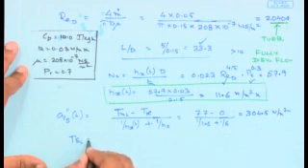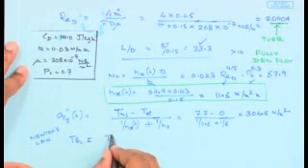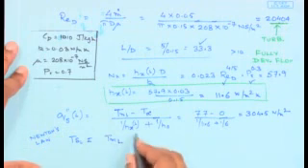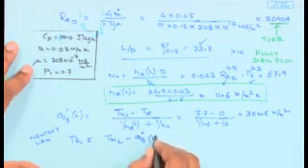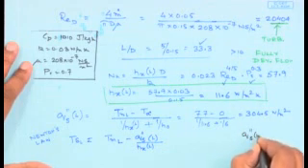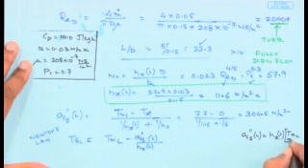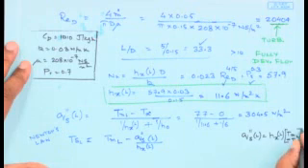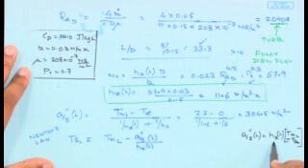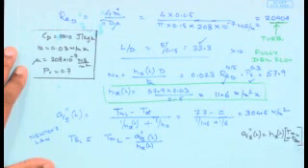And for the surface temperature T_s,L, I am simply using Newton's law of cooling, which would simply be the mean temperature of the fluid at location L minus q_s double prime, the heat flux at location L, by h_x at location L. The relation that I have used is q double prime s at location L is h at location L times T_m,L minus T_s,L. That is nothing but Newton's law of convective heat transfer, when I consider convective heat transfer from the bulk fluid to the inner surface of the tube, and this is the internal convective heat transfer resistance.